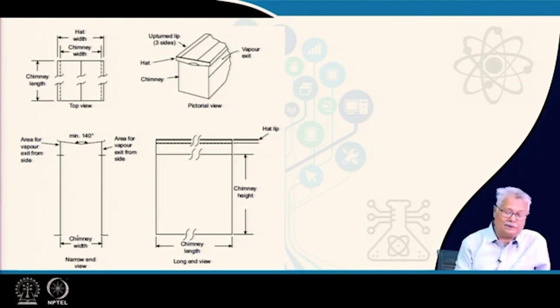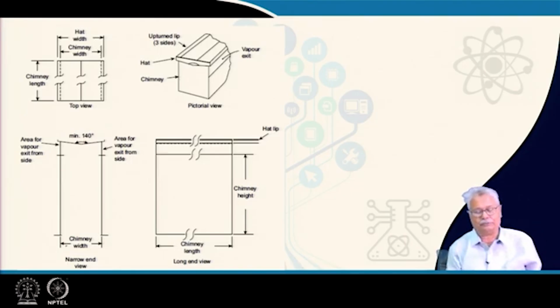The top in this particular case is not convex, it is not just a hat, it is an inverted hat. And what happens is, I have mentioned about the upturned edge of the hat. The upturned edge does one thing, it collects all the liquid on the hat and allows it to drain from one side only. So, quite naturally what you have is it will be collecting all the liquid here, and from the thinner, the less wide end, it will be draining off.